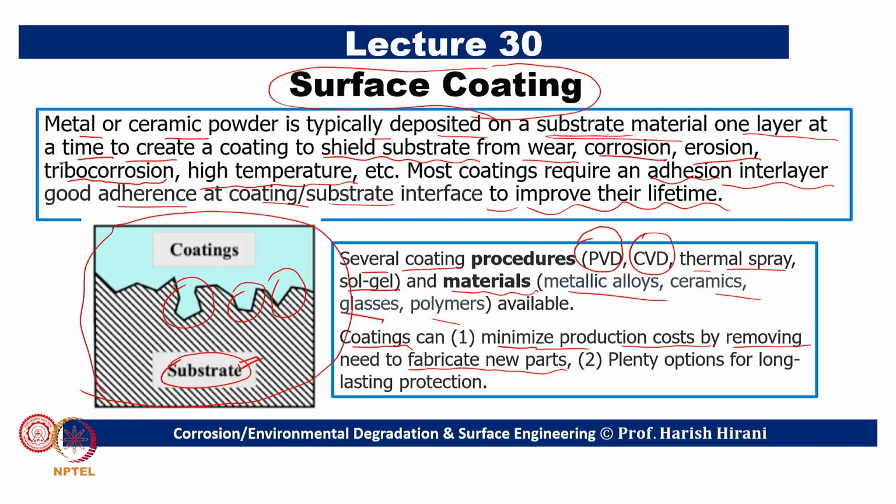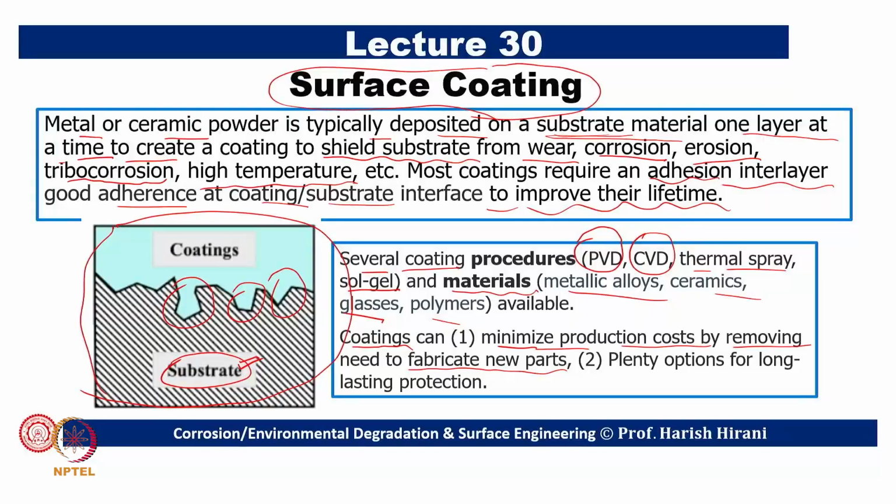Now, quite possible we may invent a new coating and then it has a different kind of functionalities. Or if we are going for the PVD or CVD, which are thin film coatings, we can go ahead with multi-layer coatings also. So, even what was not achievable in a previous component, previous subsystem or previous surfaces, that can be achieved today by just doing a few micron coating on the surface, and then you find the product has become totally new or maybe ready to move in a cyclic manner, right. So, those things are possible when we can really apply coating in a more meaningful way.